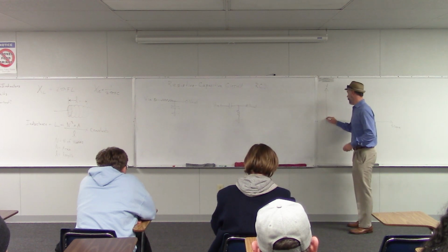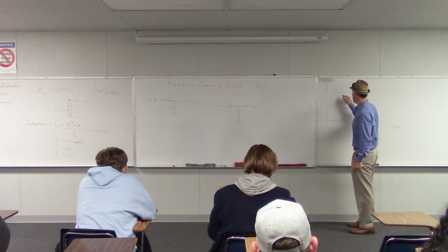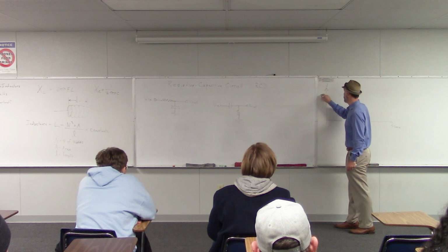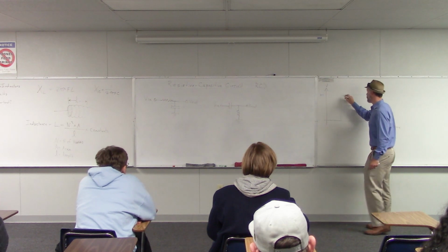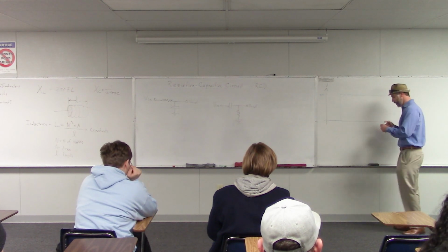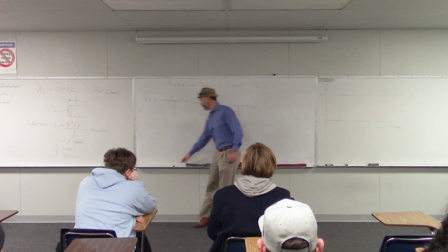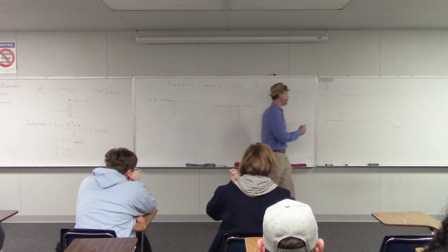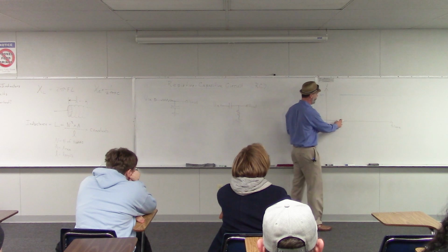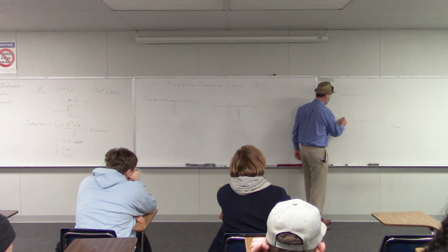At first, it's down here at 0 volts, and then at some point you change it and put it up to maybe 10 volts. That's when your capacitor starts charging. What would happen to the voltage on the capacitor is that at first, it would start to charge up really fast because there's a big difference between the current voltage and the input voltage. So it would start to charge up really, really fast.